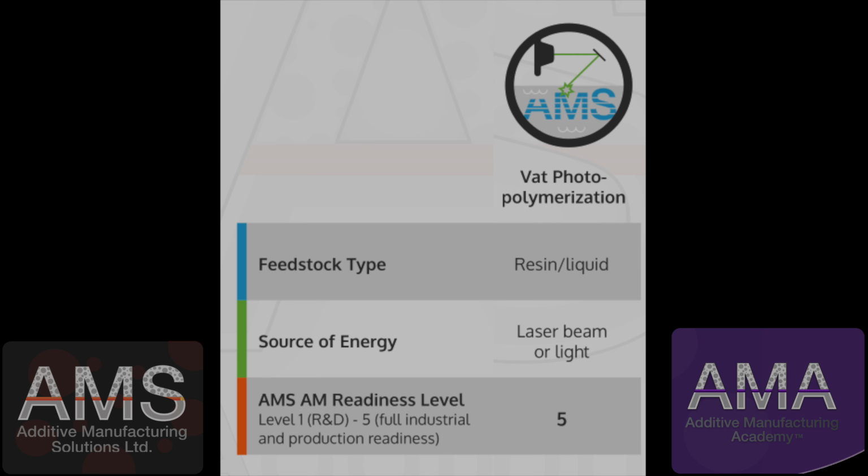It's not uncommon to find ceramic inclusions in resins which are used to create very stiff, high quality resin-based parts. They don't have the same UV degradation, they have a much stronger and more consistent performance, and that stiffness allows them to be a really good model in the wind tunnels in particular, because the stiffness can replicate that of carbon fibre parts, often found on aerospace and motorsport components.